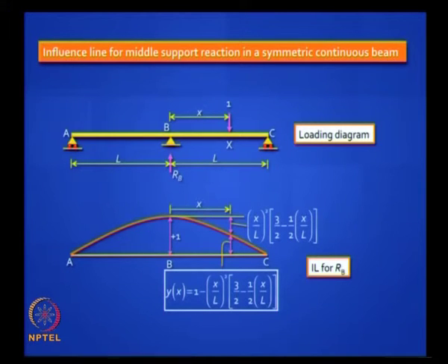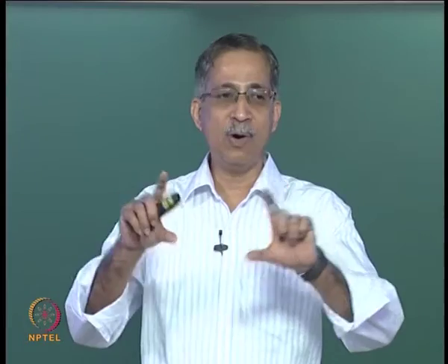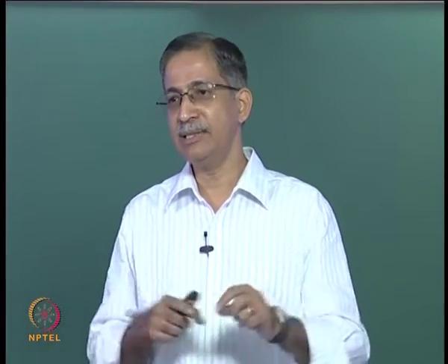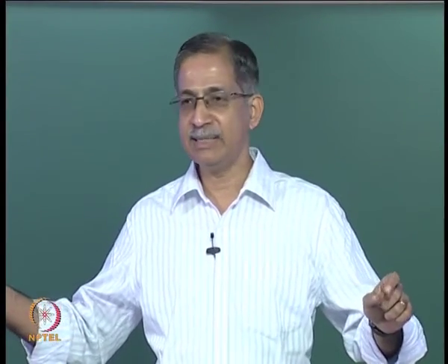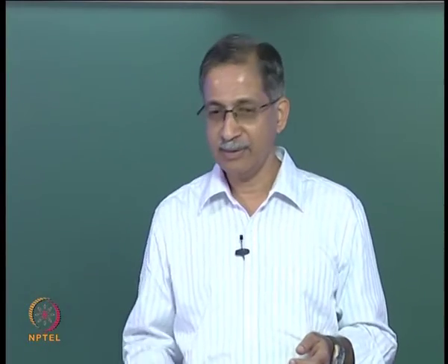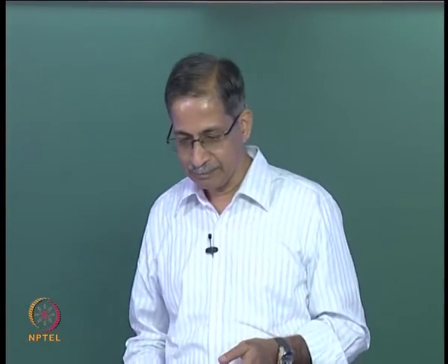There are handbooks available where they do not give you the exact equation. They are useful in bridge design, where you get the ordinates at different locations. You divide the span into about 10 segments and you get those locations, and they are sometimes used in practice.